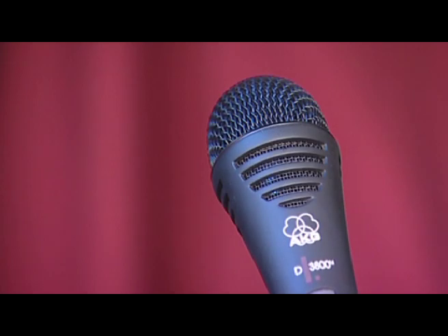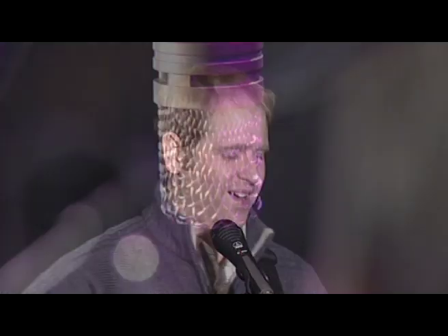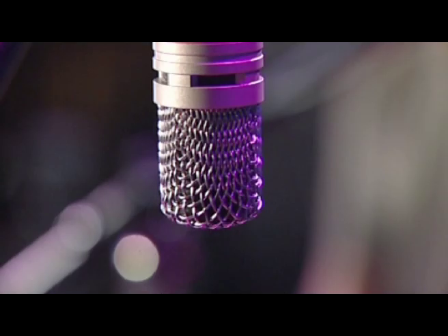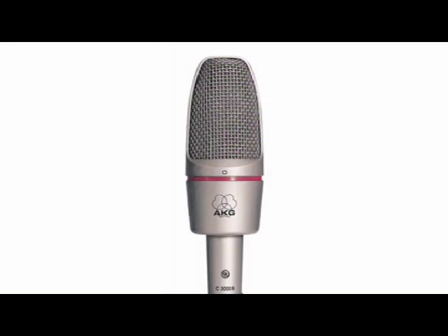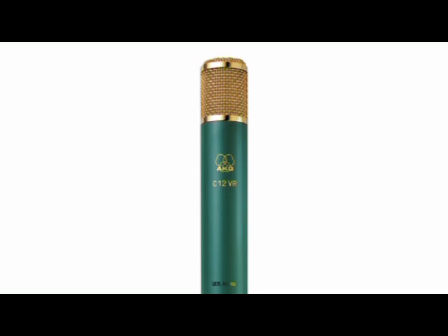Dynamic microphones are tough, tend to be relatively cheap, and don't need an external power supply. They're ideal for all-round use, and especially where there are high sound pressure levels. But they're not as sensitive to high frequencies as condenser microphones. Condenser microphones are much more sensitive to low sound levels and to higher frequencies. They need power to make them work. Some work with batteries, but most of them can also use the mixer's phantom power.